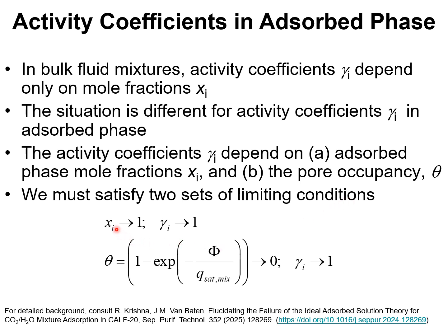As the adsorbed phase mole fraction of any component i tends to unity, the activity coefficient of that component must tend to unity. Additionally, the pore occupancy theta is related to the surface potential phi by this expression, where Q sat mixture is the saturation capacity of the mixture.